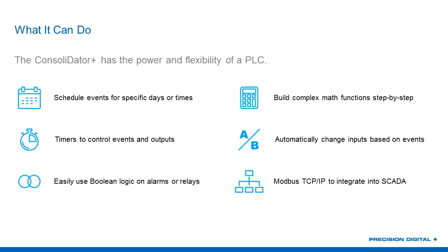And then lastly, one of the unique features that makes it similar to a PLC is the fact that it does have an Ethernet output. It supports Modbus TCP/IP, so you can integrate this ConsoliDator Plus into a traditional SCADA system. And so that's where it all ties together there. So again, that's just the basics of what it can do and the things that it can do that make it comparable to a PLC.